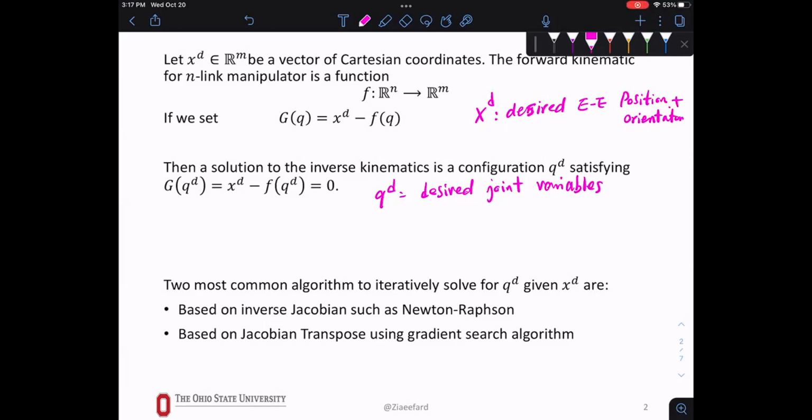Yes. So both of these are numerical, right? These days with computers doing all the cool things they do, and with the processors, we don't have a problem with the processing or how fast the algorithm is. The problem is the inverse Jacobian. We have to make sure our Jacobian is invertible, right? If it is square, then you have to find all the singularities, so make sure that it doesn't fall into singularity. Then if it is not square, how are we going to invert it? You have to do something. So that might be faster, but you have to deal with that extra work.